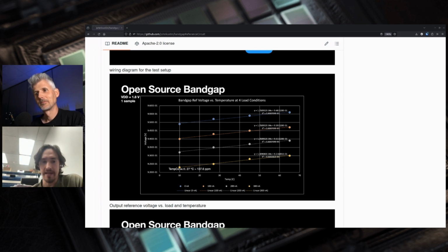For anyone who does their own bandgap, in this topology, you'll have to choose some current for each BJT, and that'll create a lot of implications downstream. And so that kind of spec, if you have to change that, then you've got to change almost every size. It's also interrelated. Analog.